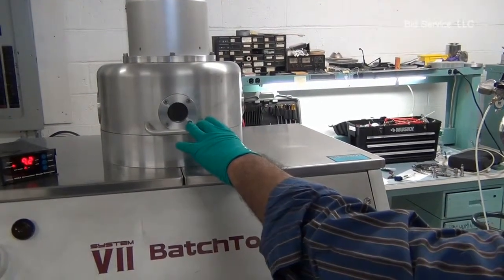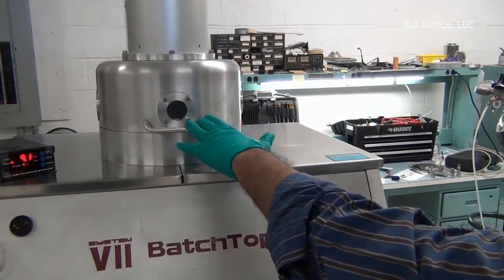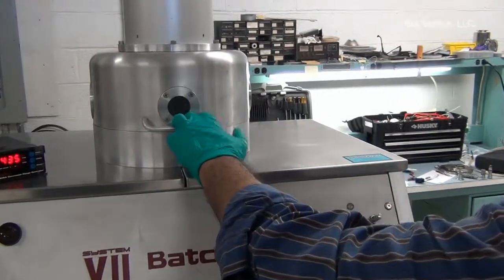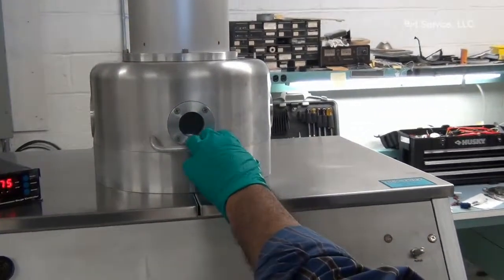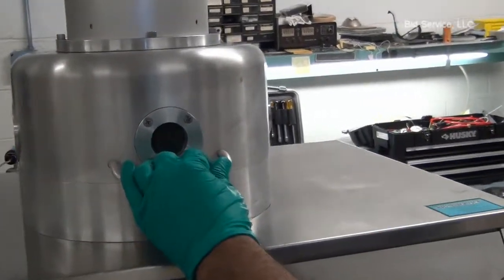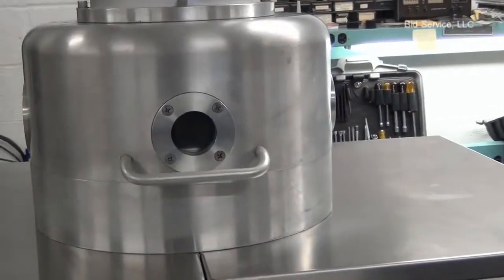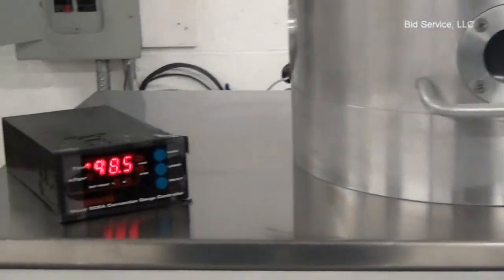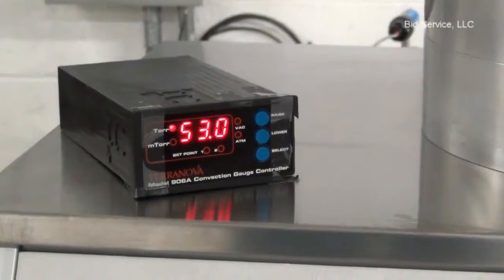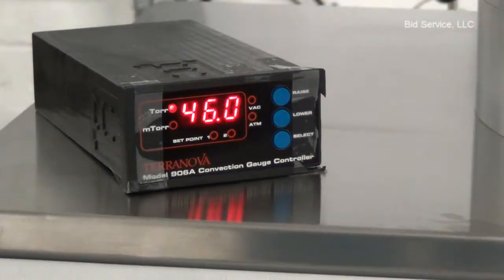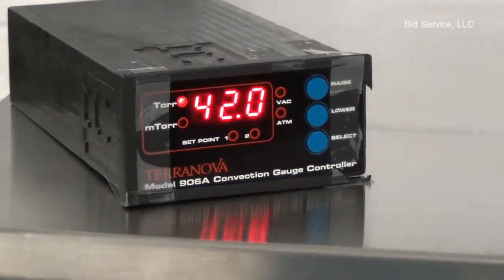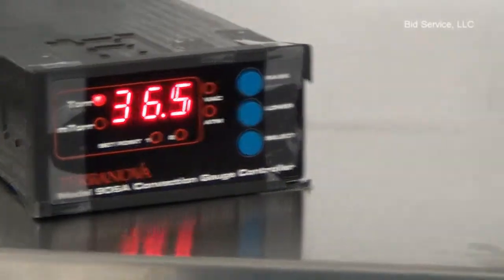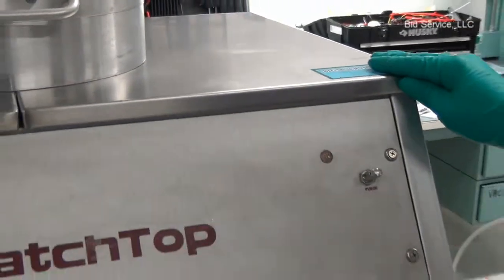Click on utilities and pump down the chamber. At the beginning of the pumping down, hold the handle down so that the sealing will be tight. The system needs cold water for cooling the electrodes.